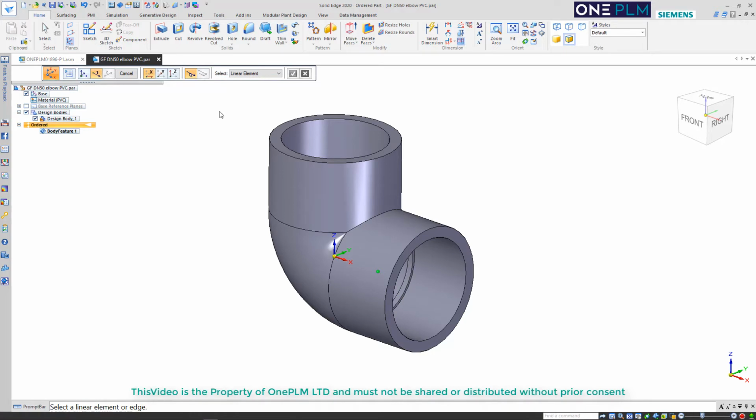So what we need to do when we've got a pipe system, we need to create coordinate systems. We need to create two for each input, one for each input-output area. So that one's going to be an input because the X is going in that direction. If we don't know how to create coordinate systems, have a look for an option for creating coordinate systems. But we can create coordinate systems quite easily, but then we need to make sure that we're naming these so it gets picked up by the standard part system.